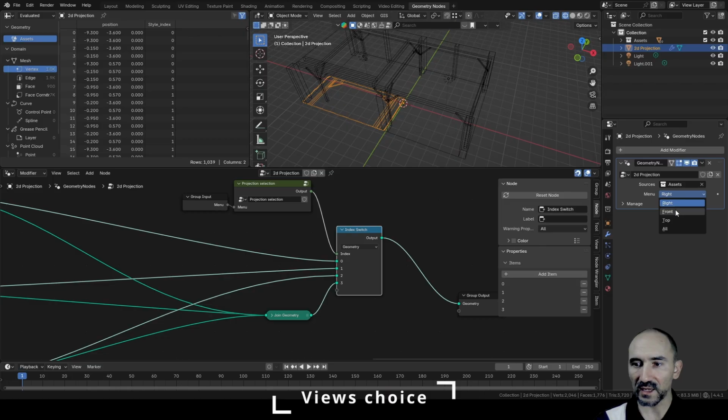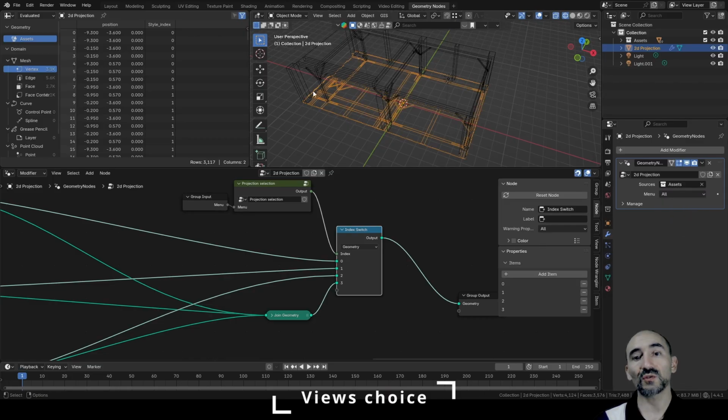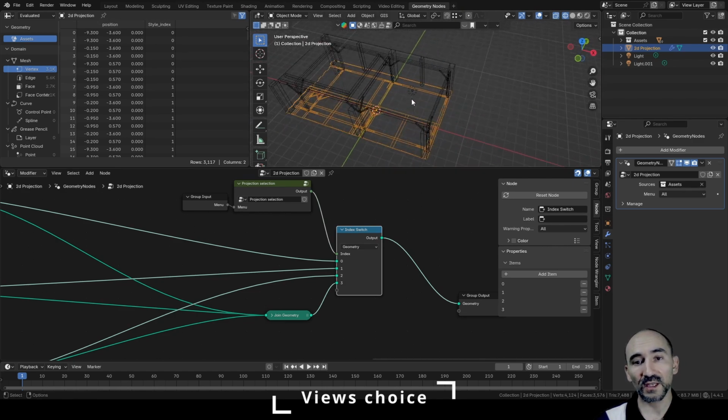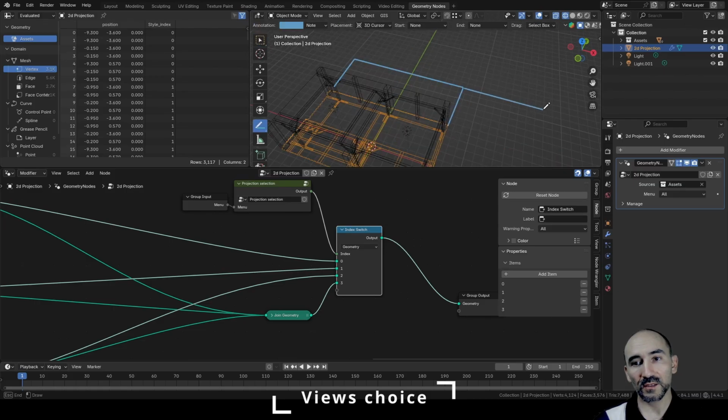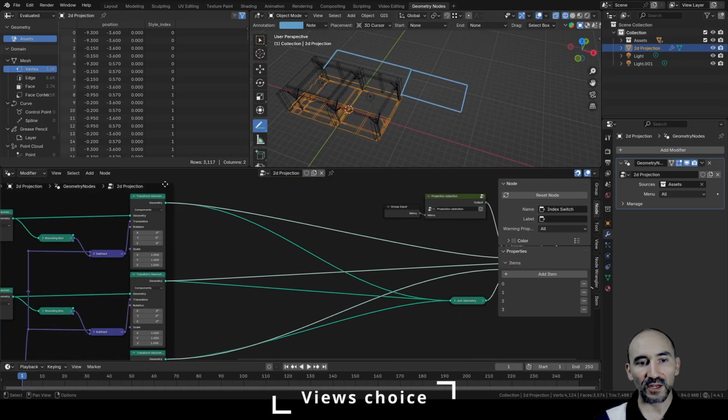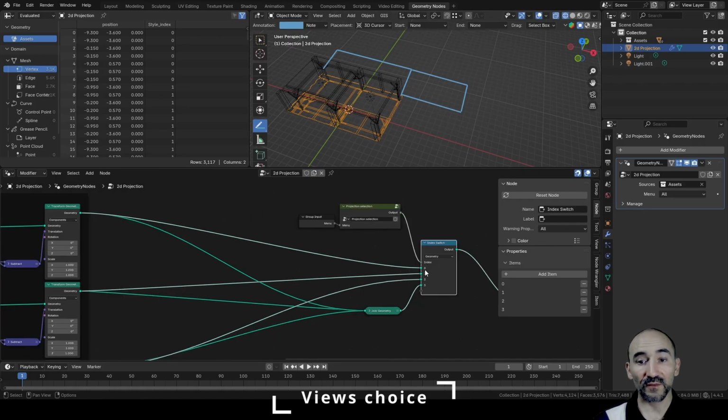So now if I select the front, the right, the top, or all these together, we can have this result. But as you can see, we have a wrong 2D projection because what we need is to have the top here, the front here, and maybe the right 2D projection here to be able to see all of them. And to do this, we need to offset the 2D projection output of this transform geometry node to have the correct result.